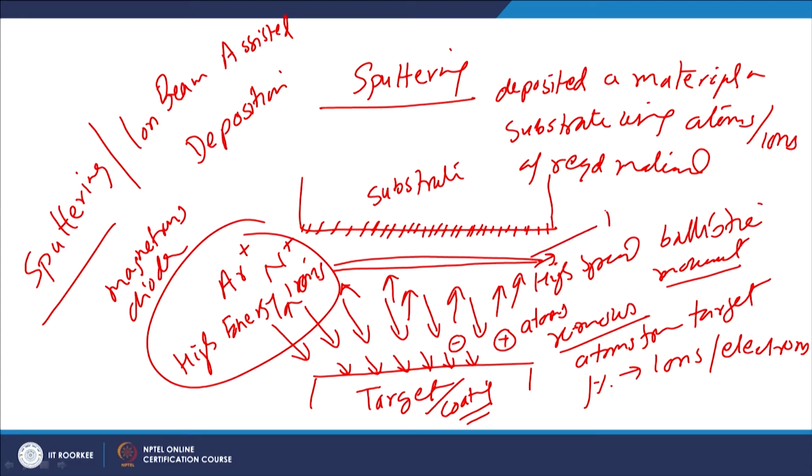So in between the substrate and the target we have a screen. We put in a potential difference between the screen and the target material, so that the high energy ions and atoms can be further accelerated towards the surface of the substrate. These are the important features related with this process.